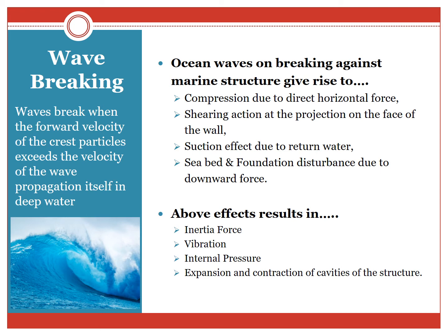So my dear friends, it is trying to say that if your wall is of a masonry structure, then it will get severe damage. But if your type of structure is mound type, which has many voids, or I may say many holes in its structure, the internal pressure gets relieved. So by this, the wave breaking will have a lesser effect on the breakwaters.